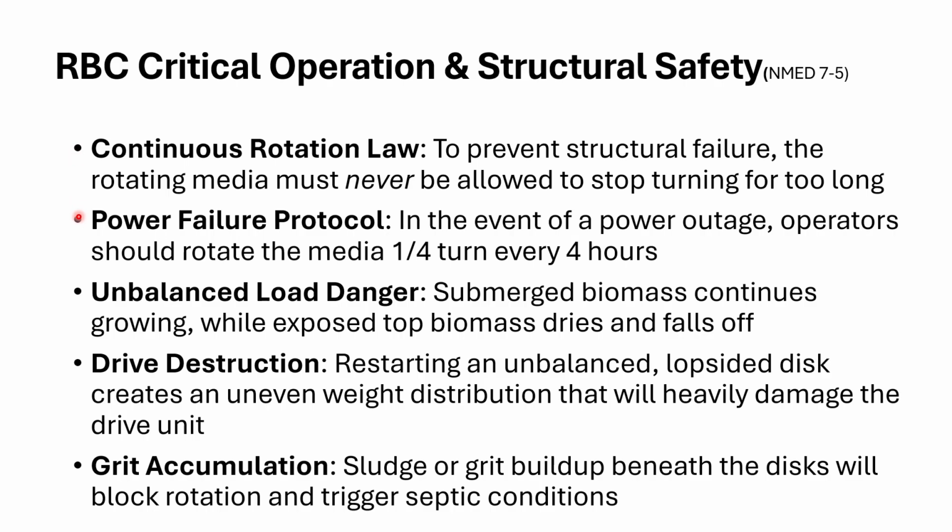And then in the event of a power failure for an RBC, you want an operator every 4 hours to make a quarter turn of that barrel. Two pretty big things. Another thing, one of the reasons we want to make that turn is if we leave that portion of the barrel submerged, that film's going to keep growing, and we're going to have an unbalanced load, just like you do with your washer.